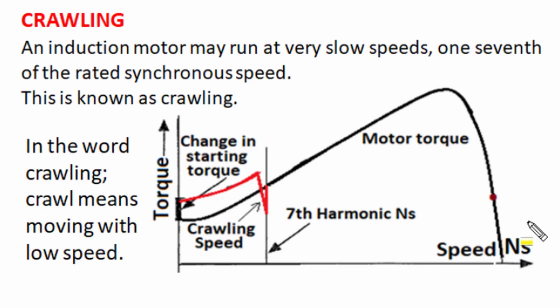Let's start. All induction motors have a working rotating magnetic field of constant magnitude and constant rotational velocity, and the velocity of the rotating magnetic field in RPM is known as synchronous speed, given as 120 F over P. It depends upon supply frequency and the number of poles in the machine. The rotor of an induction motor runs with a certain amount of slip with respect to synchronous speed, with 3 to 6% slip depending upon motoring load requirement. An induction motor attains a speed very close to synchronous speed.